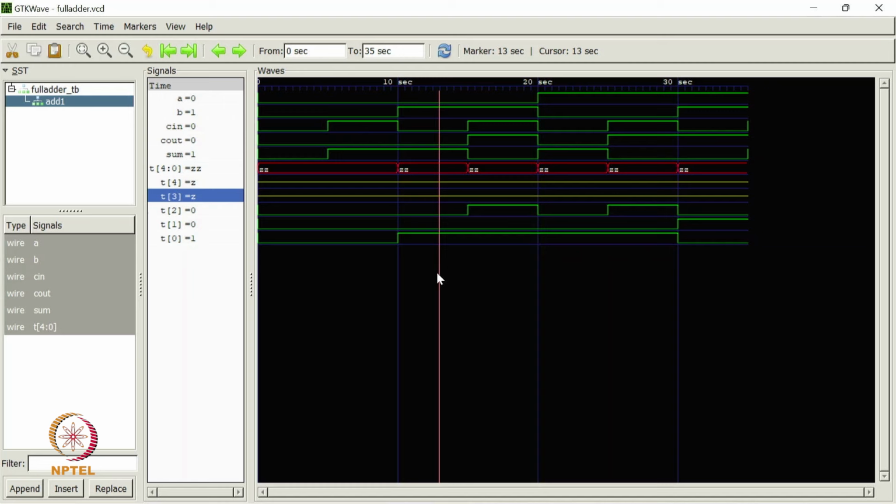So, this output can take any value which is not fixed by our circuit. If this dangling, high impedance value goes to the gate of another logic gate, that gate will not be able to predict whether it is a 0 or a 1; it can be in between. If the input is somewhere in between, this is going to create a short circuit current in the next stage. So, these high impedance states are not desirable in digital logic design.